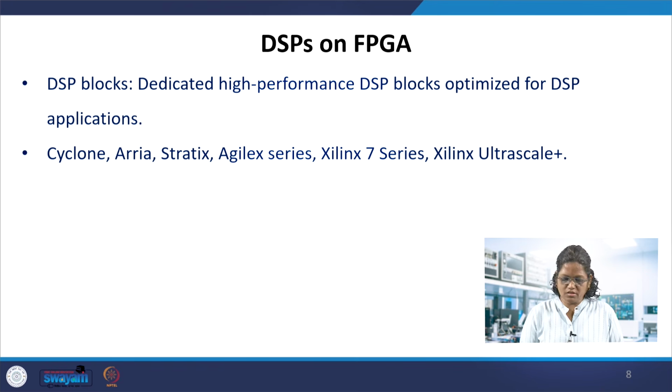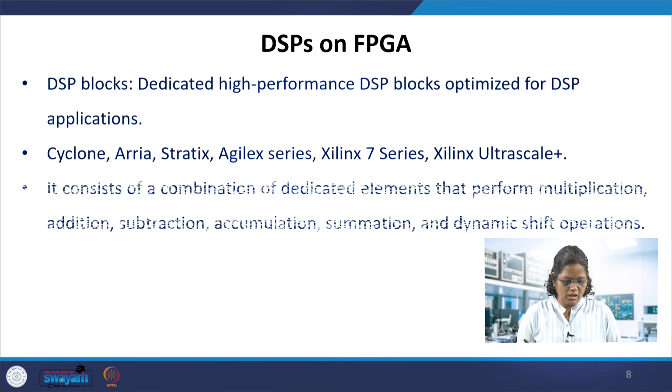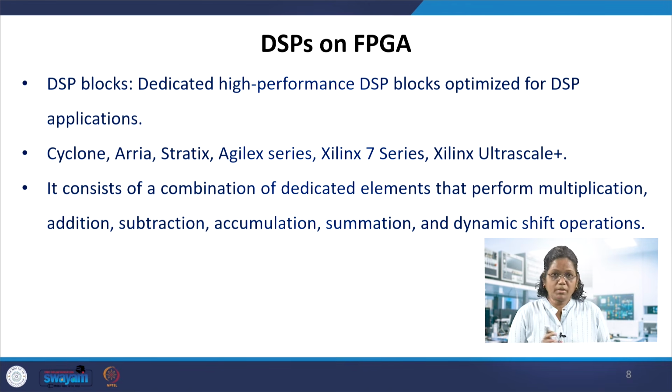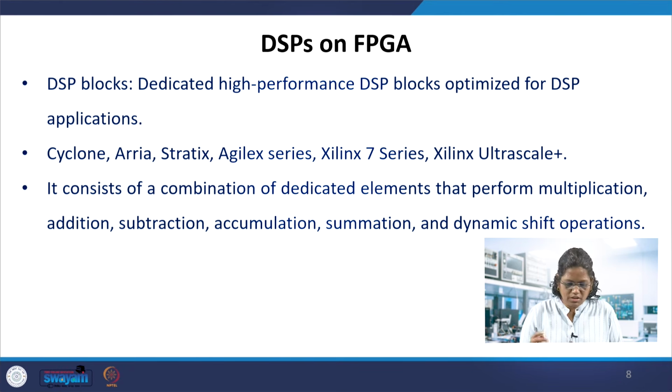They consist of a combination of dedicated elements to perform multiplication, addition, summation, subtraction, accumulation, and also dynamic shift operations. These are the main parts of the FPGA DSP blocks.